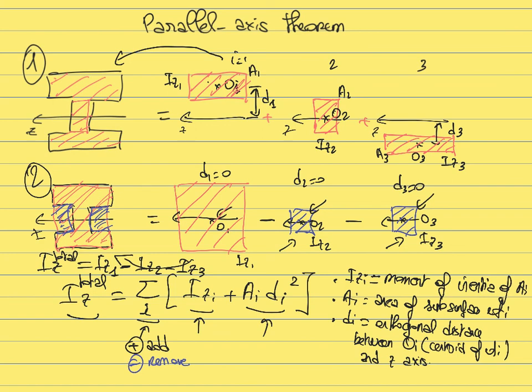And once you have the moment of inertia, this is going to give you the geometrical quantity, the moment of inertia about z, that dictates the resistance of the beam to bending about the z-axis. So this moment of inertia is going to be a key property that will be useful when we calculate the stress that is generated within a beam that is subjected to bending.